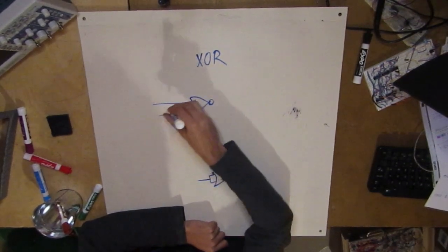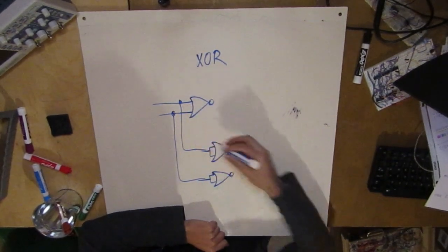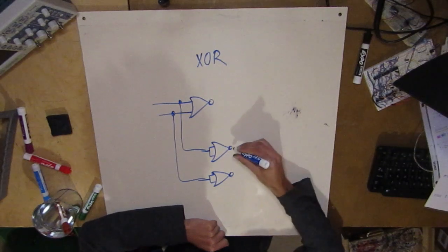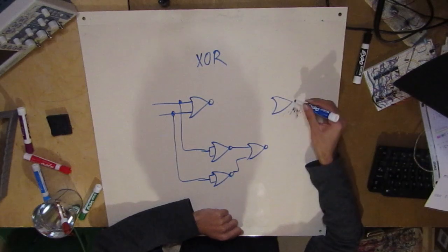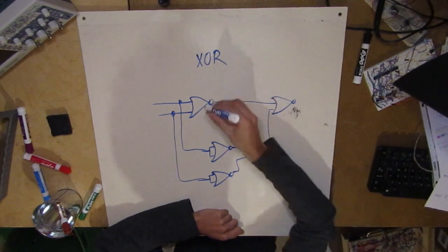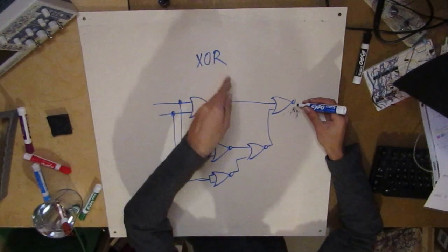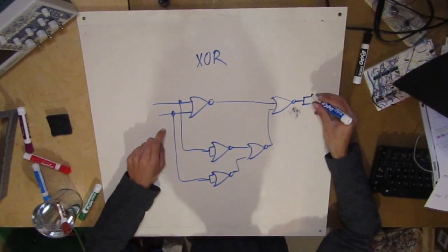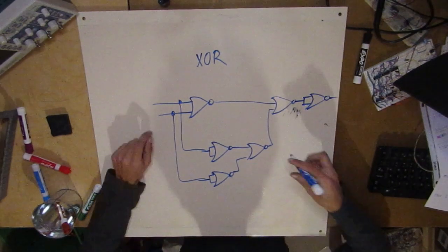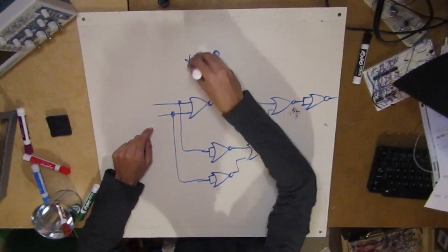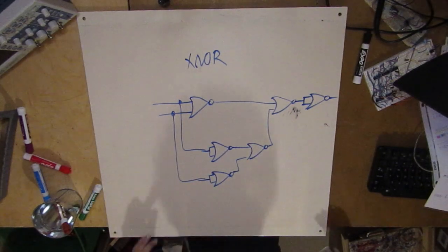So you get your inputs here. This guy's coming in, and this guy's coming in there. And they both chain up into another NOR. And eventually, they all meet up in this final stage of NORs. This is an XOR. Now if you want to be so inefficient, you could turn this into an XNOR by just chaining off that. So this is now representing an XNOR because I put this there. But this uses 6. You can make the XNOR using 4, which I showed before.